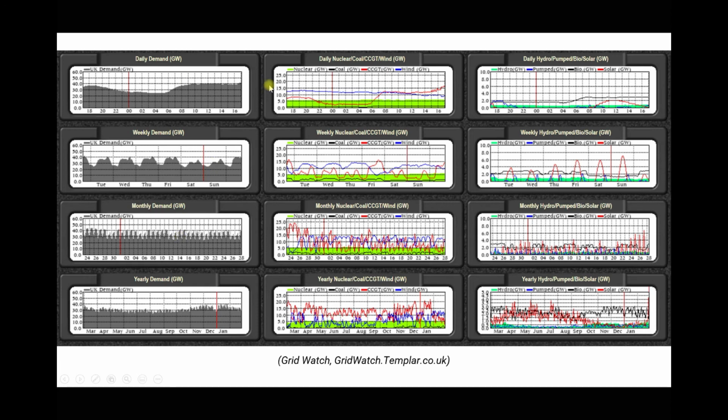The important point is our renewables provide a baseline. Our combined cycle gas turbine is used to meet demand as demand increases. And when we have peaks in demand, such as at 5 p.m. on a weekday, we can release energy from our pumped hydroelectric storage plants in order to meet that instantaneous demand. The eventual goal then is to rely solely on our renewable energy sources such as wind and storage technologies such as pumped hydroelectric storage, and other energy storage methods are available and currently being developed.